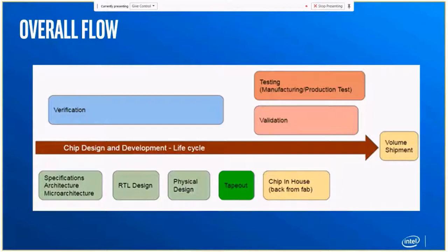Tape out is the standard terminology in the industry, but within Intel, I have that in one more slide also. We also have this notion of tape in. Because we have huge SOCs that we are putting together for which different block IPs come from different teams, they all need to be stitched together into one SOC. So when we reach a point where we have all the individual IPs ready to be connected together and made into one SOC, that point in Intel terminology is called tape in.